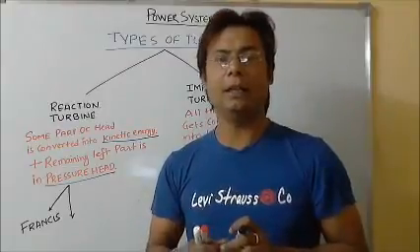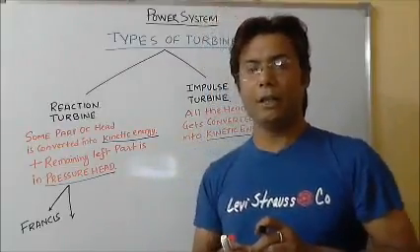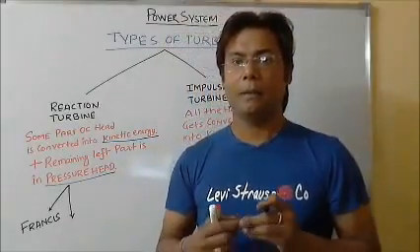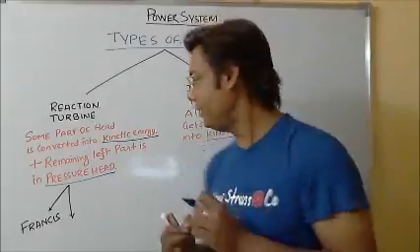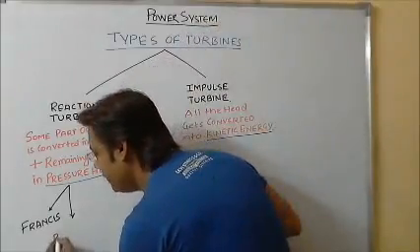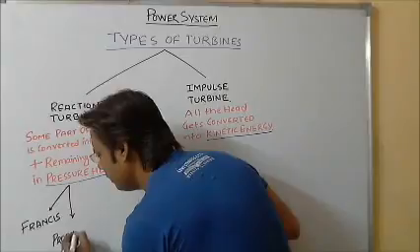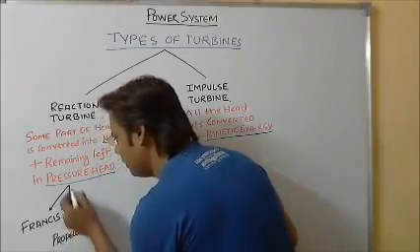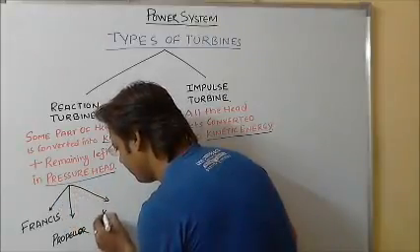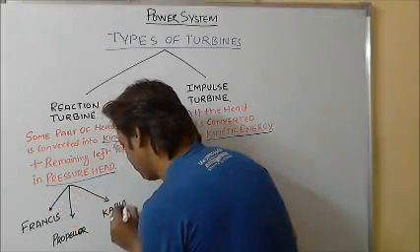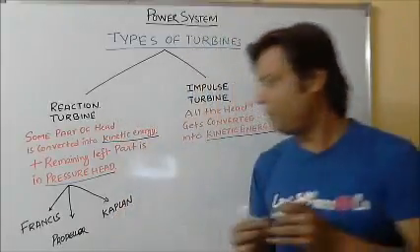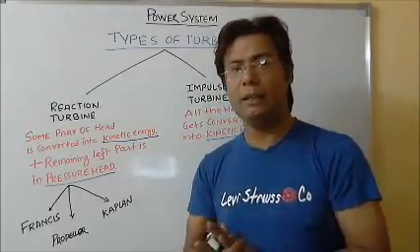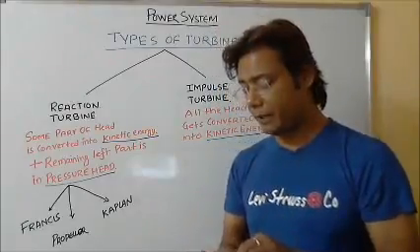All these are under the reaction type of turbine, where some part of the head is getting converted into kinetic energy, and the remaining part is in the pressure head only.